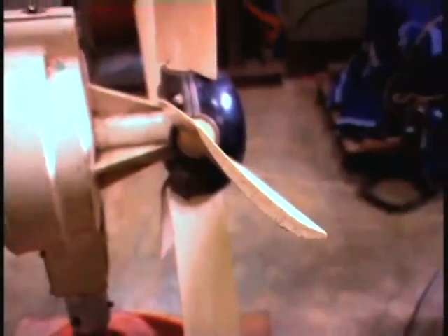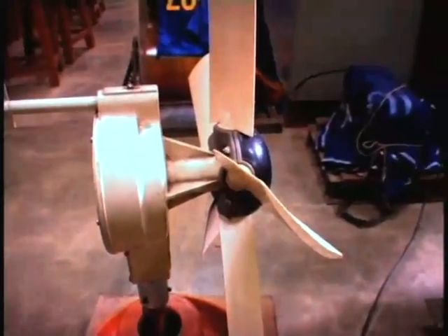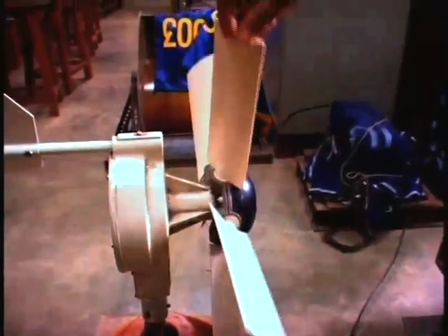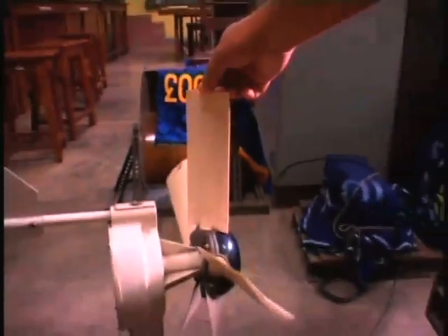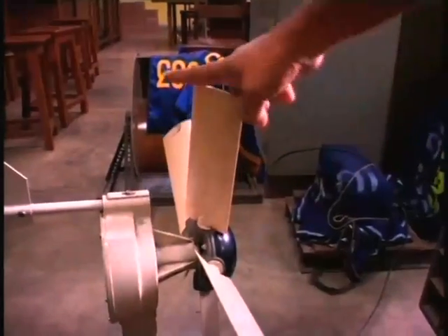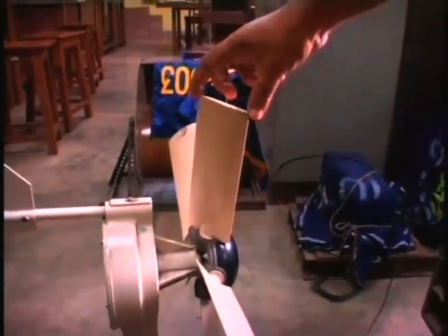What you can see now is the airfoil profile, which is, as you can see, as it is zooming back, you can see that it is inclined at an angle to the plane of rotation. And actually this is the plane of rotation, and these airfoils are inclined at an angle. So the chord is inclined at an angle to the plane of rotation, which is the pitch angle. As you can see, the wind is blowing from this side and it is rotating this way. So the relative wind is along this direction, and this pitch angle has to be so aligned so that the blade chord is aligned to the direction of the relative wind.